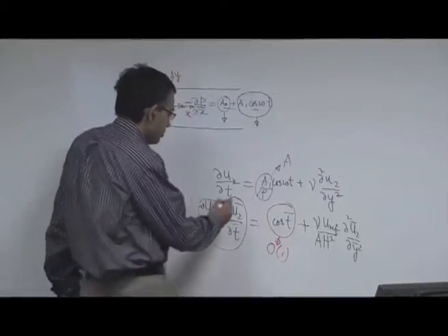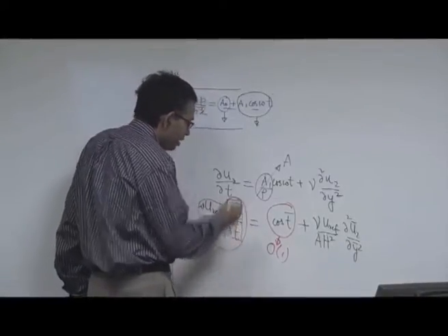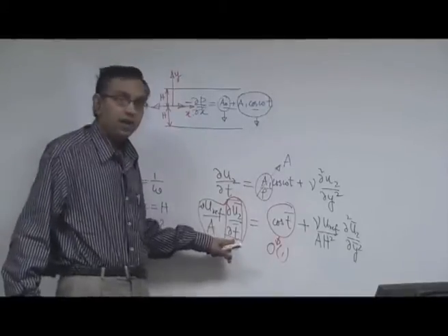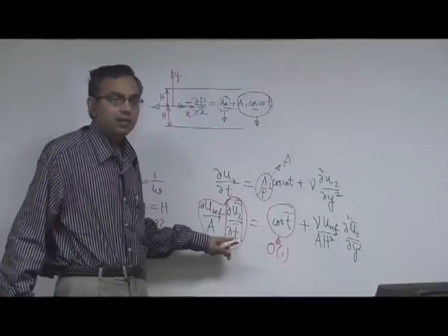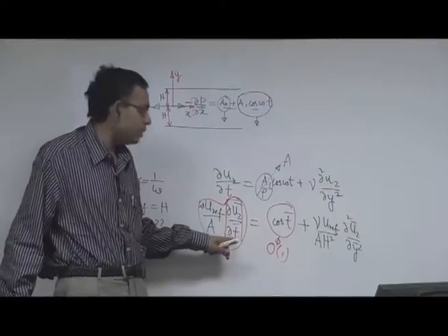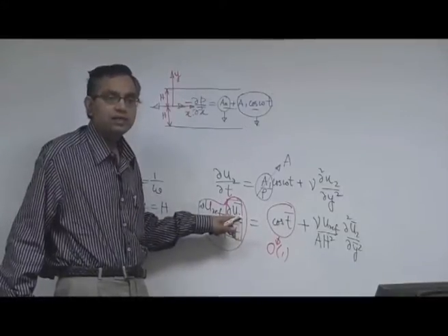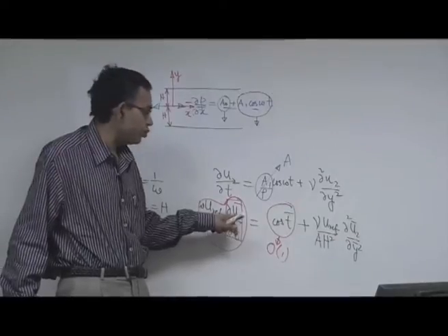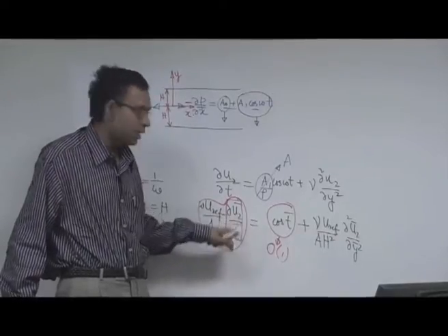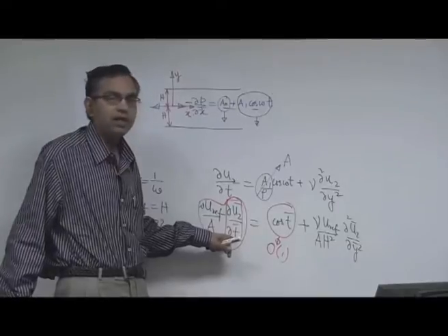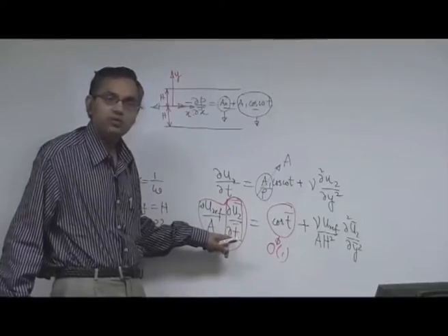Now, this particular term is constrained to be of the order of 1 by virtue of non-dimensionalization, because you have non-dimensionalized u2 with respect to its reference value, so that is u2 by u reference is of the order of 1. You have non-dimensionalized the time by t reference, that is also of the order of 1.